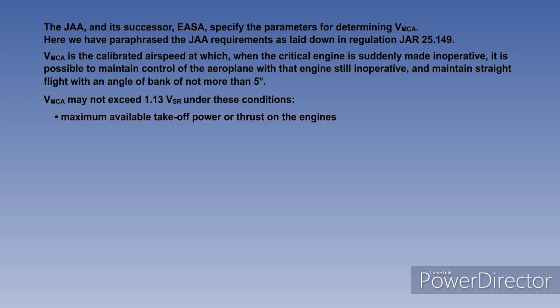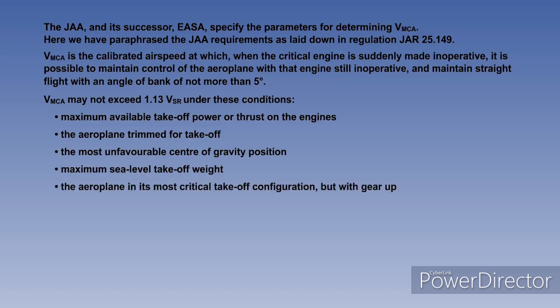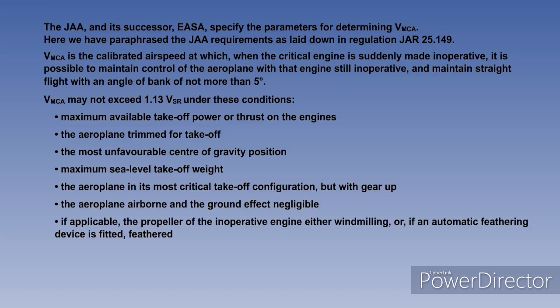under these conditions: maximum available takeoff power or thrust on the engines, the aeroplane trimmed for takeoff, the most unfavourable centre of gravity position, maximum sea level takeoff weight, the aeroplane in its most critical takeoff configuration, but with gear up, the aeroplane airborne and the ground effect negligible, and, if applicable, the propeller of the inoperative engine either windmilling or, if an automatic feathering device is fitted, feathered.